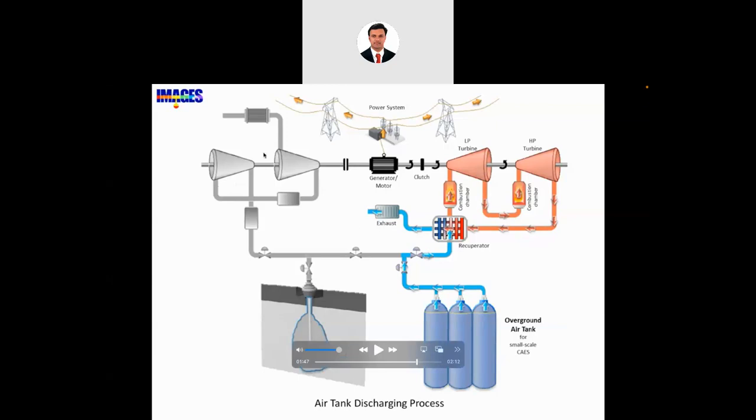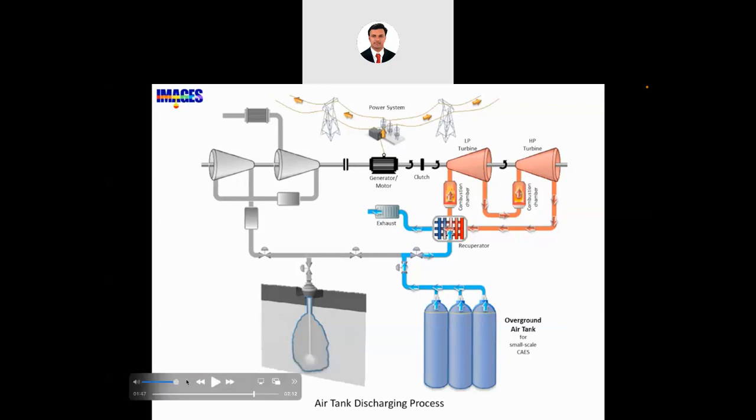It is similar to a gas power plant that we are using for this particular storage. First of all, these compressors will run on the excess power coming from the grid or from any particular power plant. During that time, the compressors will compress the air and store it in the cavern or any underground air tank or overground air tank.